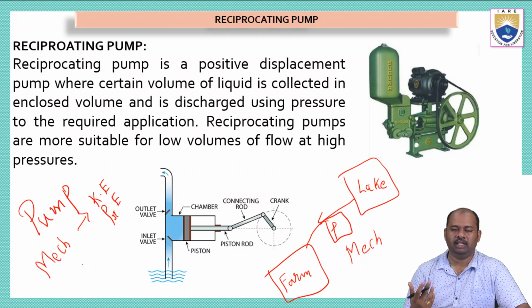So I will use an internal combustion engine or an electric motor attached to this pump. Now when I switch on this motor or IC engine, it will rotate. It will also make the pump rotate. When the pump is rotating, it will create a suction so that water will enter into the pump, and from there the pressure and the velocity of the water will increase, so that the water will forcefully enter the pipe that is attached to the farmland, where the water will be supplied to the farm. Now we have understood the basic working of any pump.